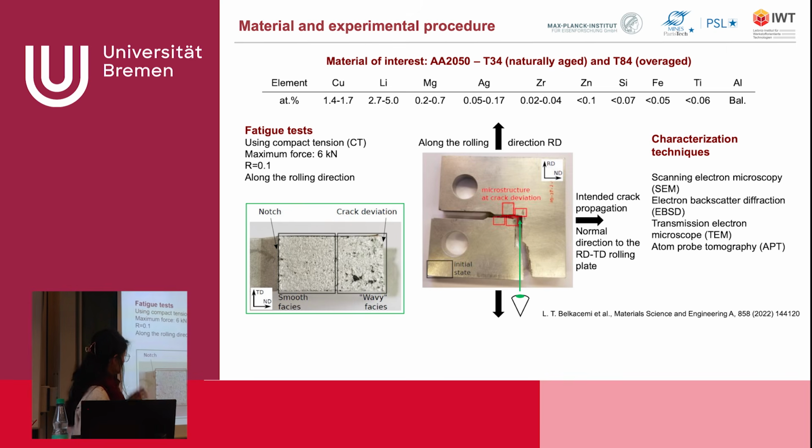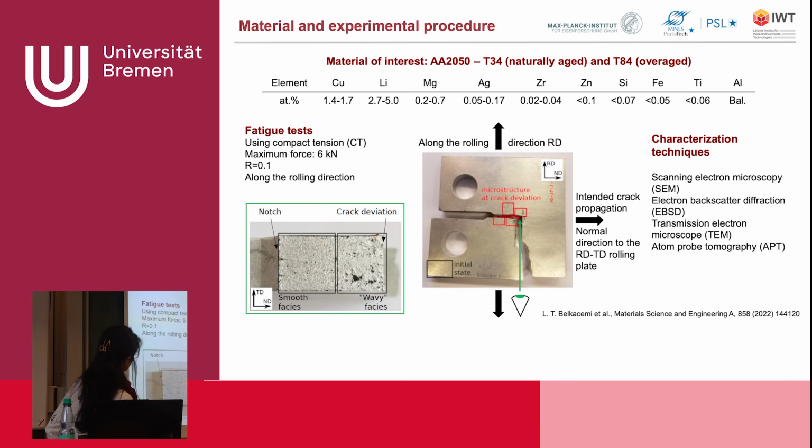There have been some tests performed on this material of interest, which are fatigue tests here, and then we had 2 versions of the material, one that is naturally aged and the one that is overaged. So naturally aged is just like at room temperature, because we expect that the material would change at room temperature because of the lithium. It's so light, and even at room temperature it can migrate.